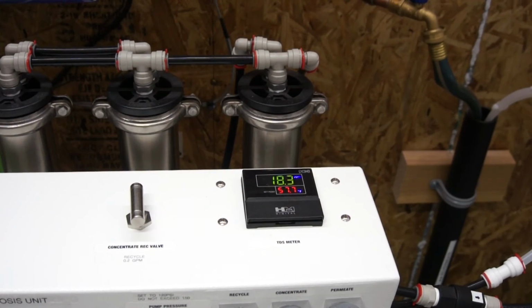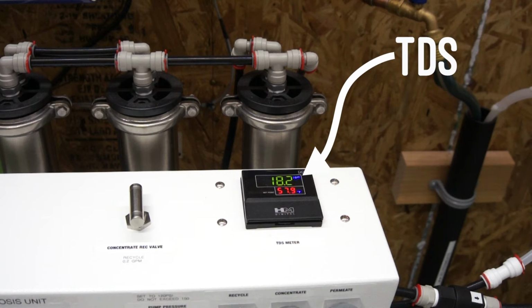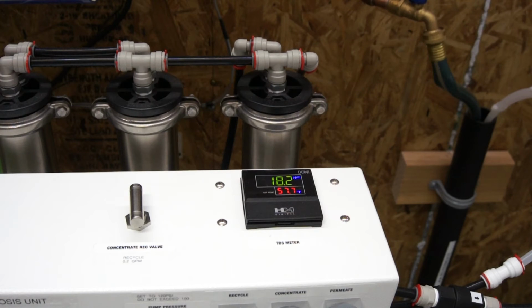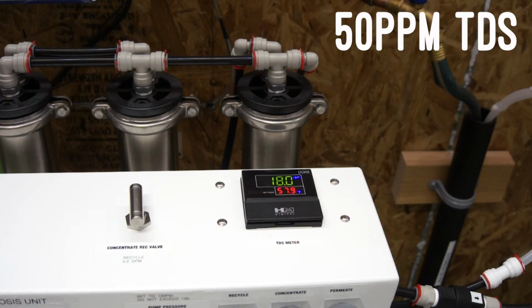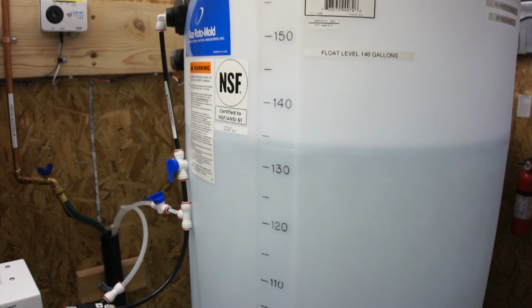RO performance is contingent on two things, TDS and temperature. Higher TDS and colder water both reduce the output of the RO system. Those ideal conditions I mentioned earlier are 50 parts per million TDS and 77 degrees. Our water is 1900 parts per million and 58 degrees. At those conditions, the 1000 gallon per minute system really only makes 700 gallons.